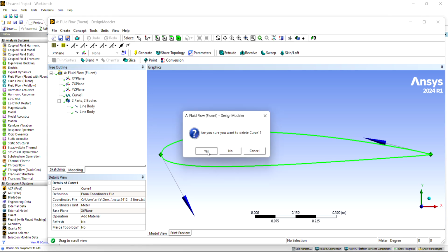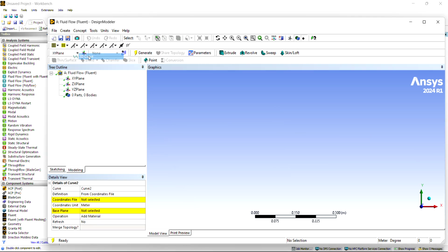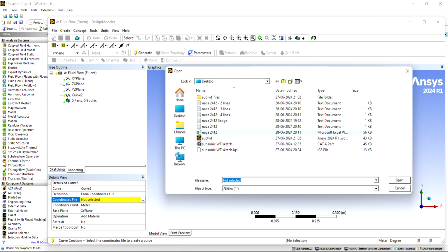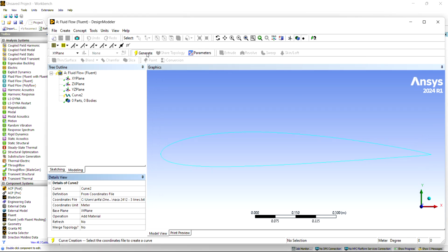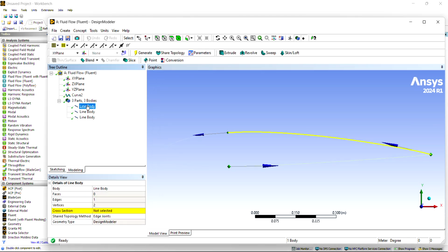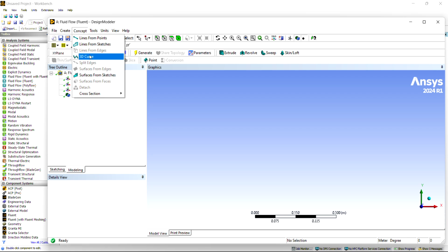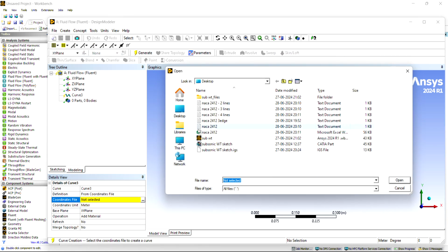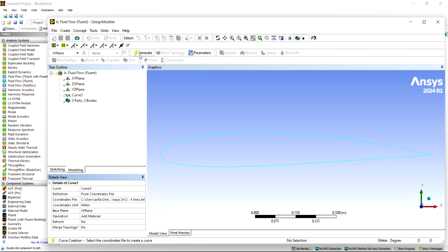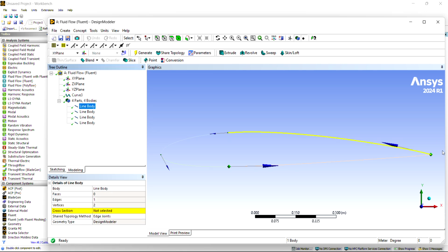Instead, if you use the 3-line file and generate, you see first from 1 to 25%, then the full front curve, then the lower surface 25 to 1. Like that you get it. And if we import the fourth one, the 4-line file, and generate, it goes from 1 to 25, then 25 to 0, then 0 to 25 on the lower surface.